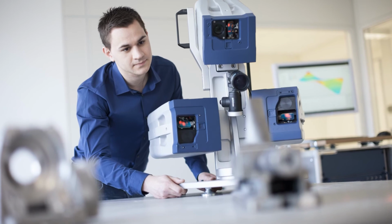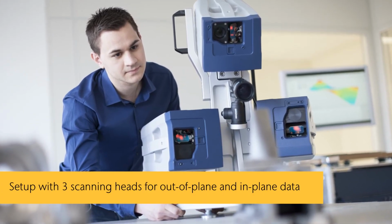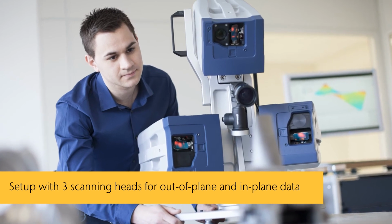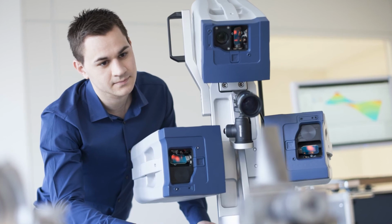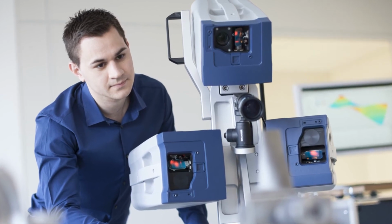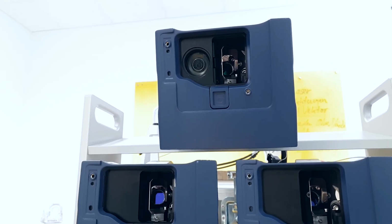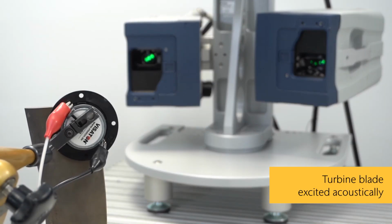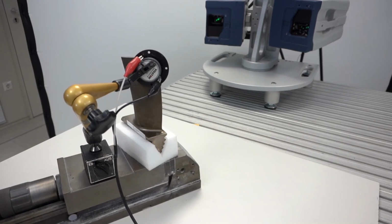Due to its very high sensitivity and its ability to measure displacement in high resolution in all spatial directions, the non-contact PCB 3D scanning vibrometer is ideally suited for comparing the simulation results with the strain and stress distributions. The typical setup comprises a 3D scanning laser vibrometer, the specimen supported in the fixture, and an exciter which allows for repeatable excitation.